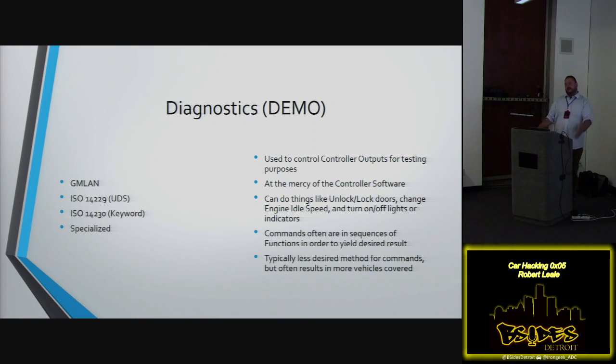And how do we fix that? Do we just stop diagnostics? That's the thing. Like, can you just stop the ability for the user to do diagnostics? Oh, well, we can just limit. Right now, the challenge is if I am a user and I do an input and I try to turn my windshield wipers on, the diagnostics has priority. And so maybe we just change the priority system. So now if the user turns the windshield wipers on and changes that switch, it actually overrides the diagnostics, which is probably a good safety feature.